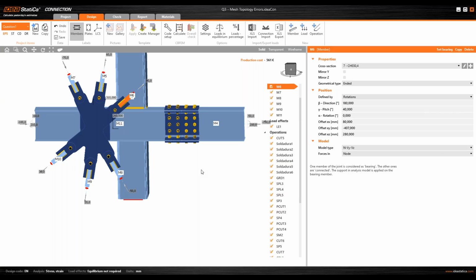It is because the DXF file from the top view is perfectly defined, but when we move from the top view to the side view, we rotate the model, we can see that there are several levels or several elevations for each line. So there is not a closed contour to generate the plate. So it is important to take care about it.